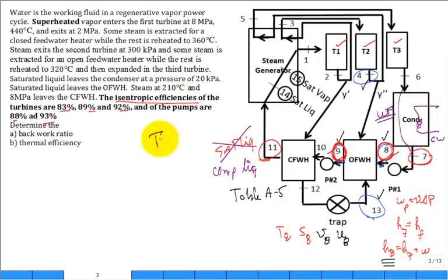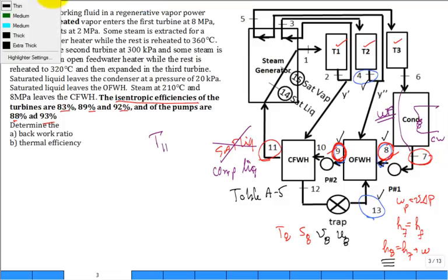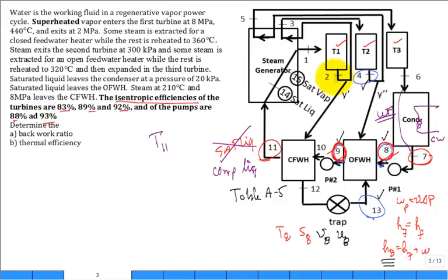What about the temperature at 11? Can you compare it with one of the other temperatures? Let's say, can you compare it to either the temperature at 2, the temperature at 10, the temperature at 12? Compare it to temperature at 2, because that's the highest temperature coming into the system. Can the temperature 11 going out of the system be higher than the highest temperature coming in? It doesn't make sense for it to do so. You're going to find that temperature 11 needs to be less than, or possibly theoretically it could be equal to, T2.